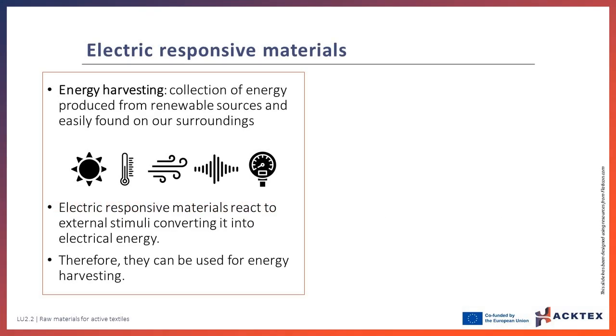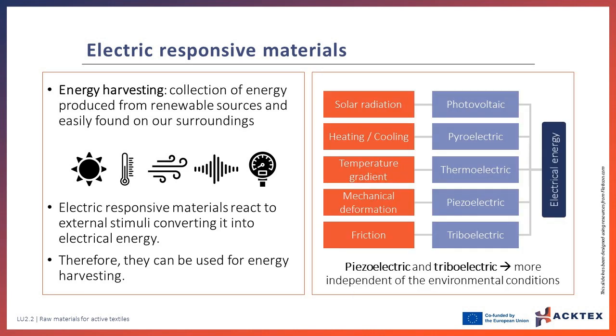The energy harvesting concept implies the collection of energy that is produced from renewable sources and easily found on our surroundings, such as sunlight, heat, wind, vibrations, pressure, etc. Energy harvesting materials are active materials that respond to external stimuli such as solar radiation, heat, mechanical stress or friction, by converting them into electrical energy. From all those examples, piezoelectric and triboelectric materials present a higher independence of the environmental conditions, so they are an interesting solution for their application in smart textiles.